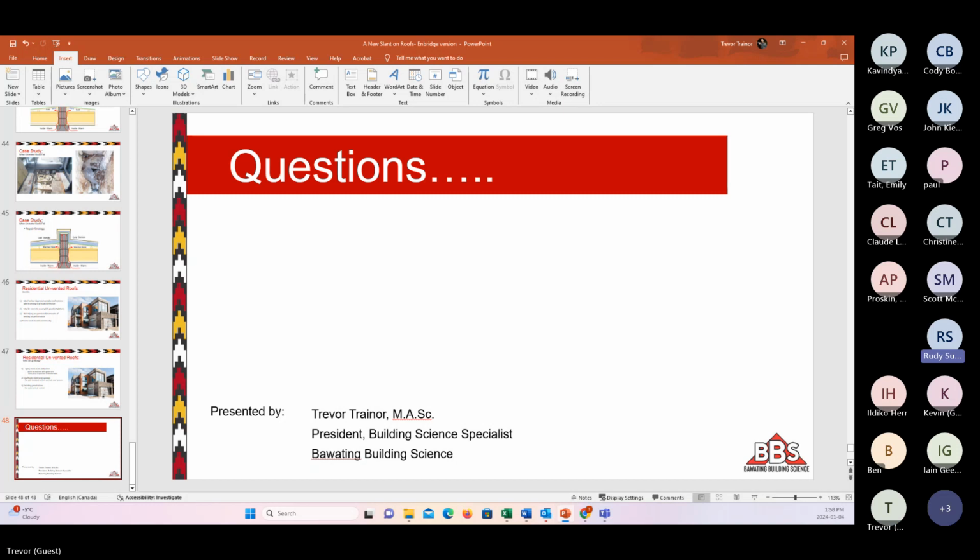Okay, yeah, that's basically what I was looking at. Up here in Kamloops, I don't like to see it, because I do see moisture creeping back into the attic, even though the attic might be well vented. That area is usually where the moisture is driving itself back in, in most cases wind driven.